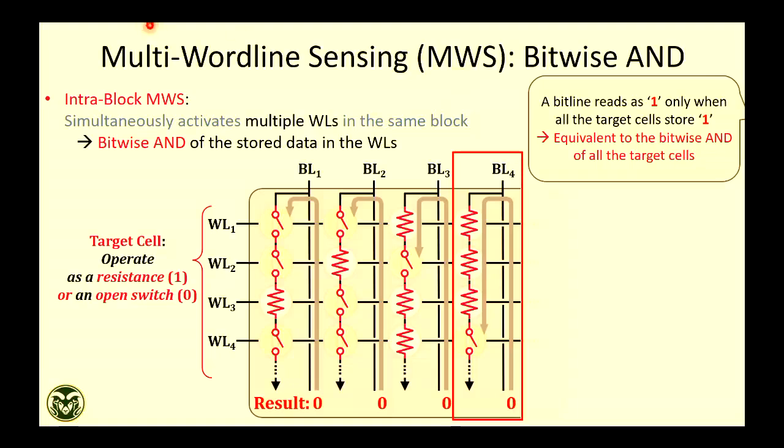Any thoughts? So here every cell is just storing one bit, either 0 or 1. This is their proposal in their Flash Cosmos paper. But what are the drawbacks in this paper? So yes, theoretically you can do this process. Theoretically, Ambit and Flash Cosmos, you can implement on the same hardware. But practically you cannot, because if you look at any chip, they will never allow you multi-word line sensing.